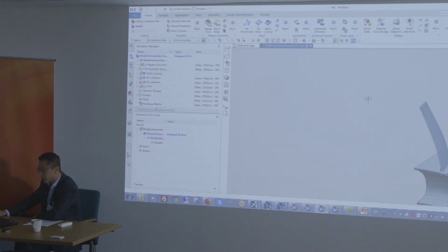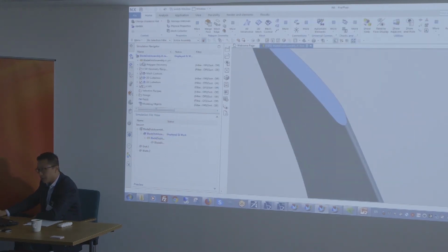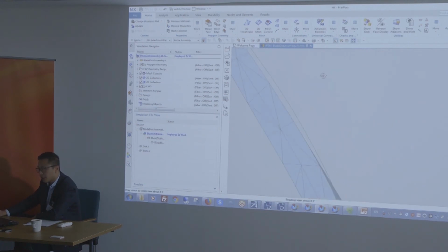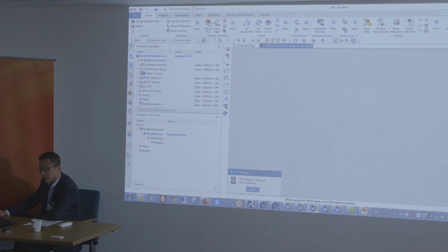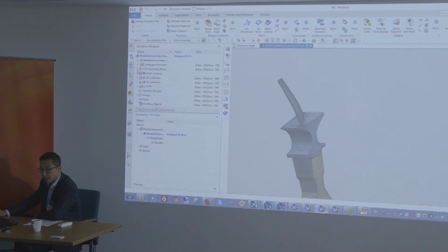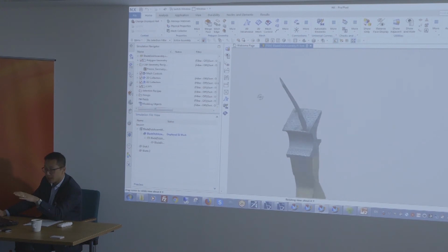Okay. So I'm not sure if you can see it. You'll see the current mesh, and you'll see the new mesh that needs to be created. Right? So that's the new edge. So that's what we can do. We can update it here. Okay, so then the mesh has been automatically updated. If you had connections, those would also regenerate. If I had mesh mating, this would also be regenerated. And the elements use the same material properties as the previous ones.